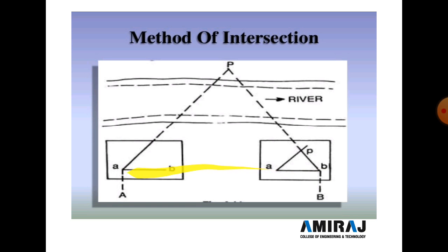From the B point, bisect the A point ranging rod and draw the line ba, since AB is already drawn. At the same time, touch the alidade at B and bisect the P point.